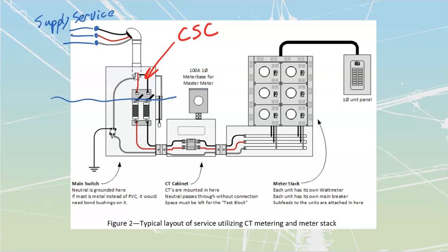Over here, we see the control device is going to be a 2-pole switch. It's going to be a common handle switch over here. So these ones will be interlocked to that handle, followed by a set of fuses that we have over here inside of fuse holders. At that point, past there, we are going to become a feeder. From here all the way through into this section is all going to be feeders, because they are feeding to other pieces of equipment that are going to feed out to individual components.